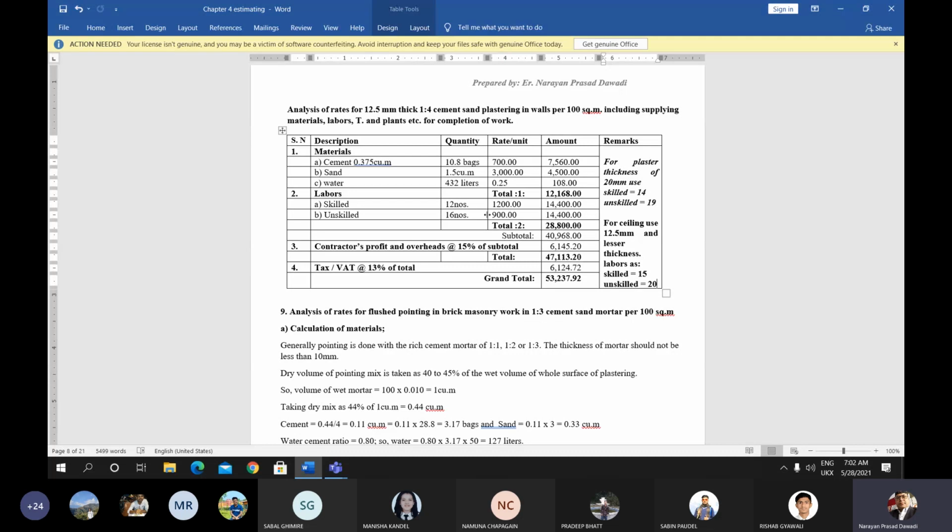You will find the volume of cement, and we multiply that volume of cement by the proportion of sand. You will get the value of sand. After finding the material, you can use the procedure in a similar way, considering 3% of labor cost for the scaffolding also. I have not mentioned it here. Please note that it must be included here.